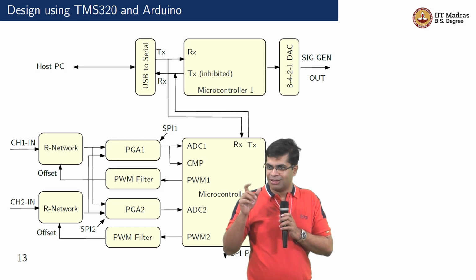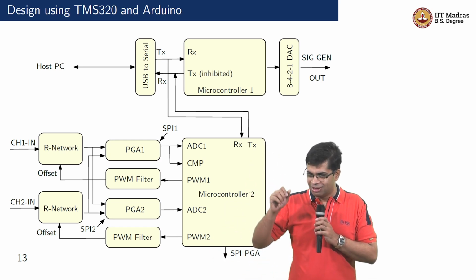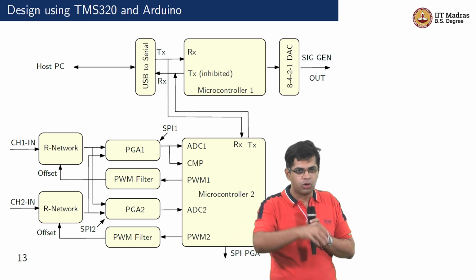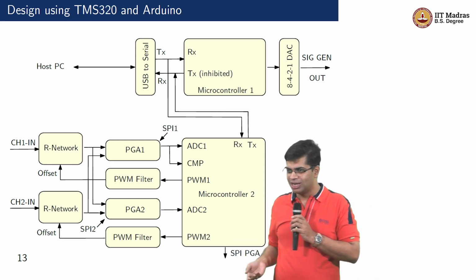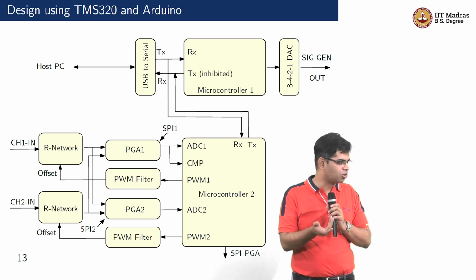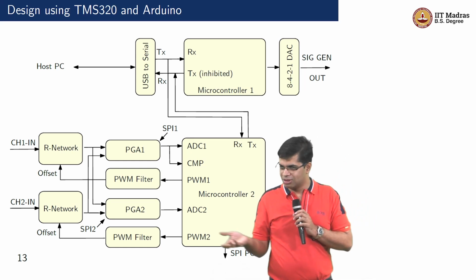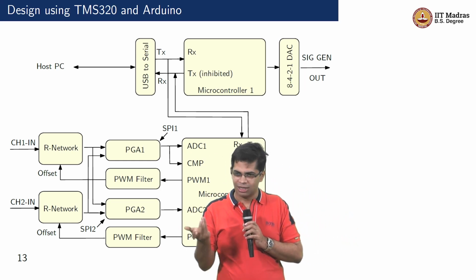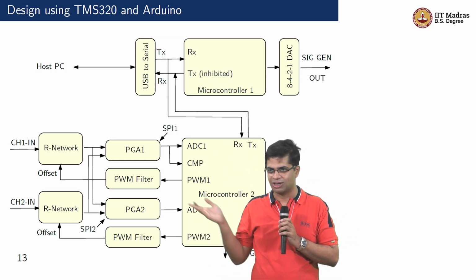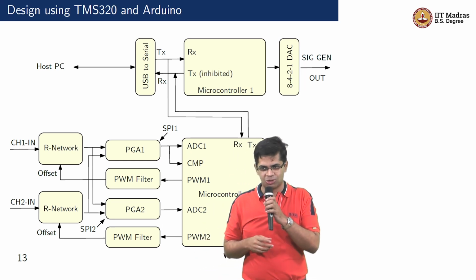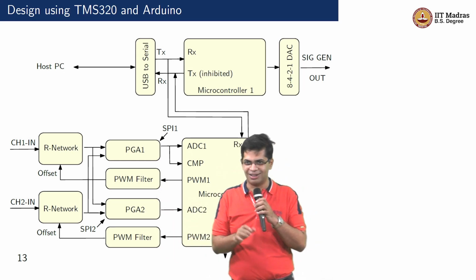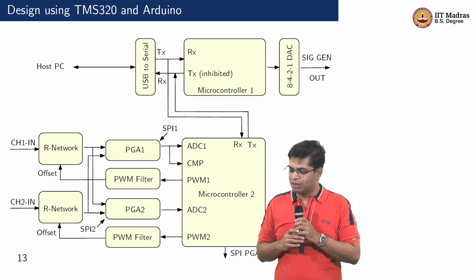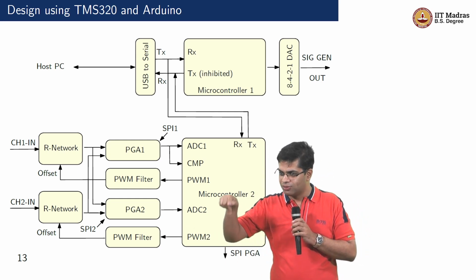Once you've done that, you then have to remove the photo paper and put it into an etchant. Ferric chloride is one etchant, but it's messy. We used hydrochloric acid, HCl, with H2O2, hydrogen peroxide. That works better. It's clean. Otherwise, our lab maintenance person will come and shout at us if we pour ferric chloride down the drain. It corrodes. So this is easier for us. And then you have to drill wherever you have the through hole components.